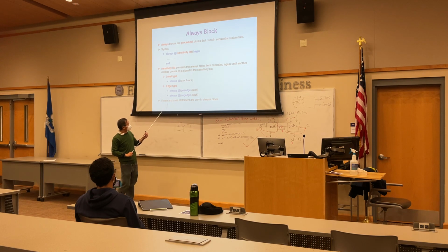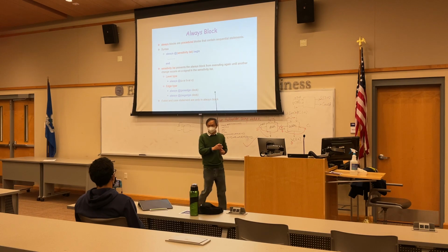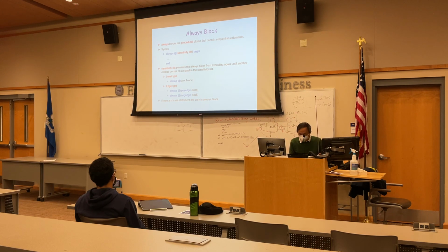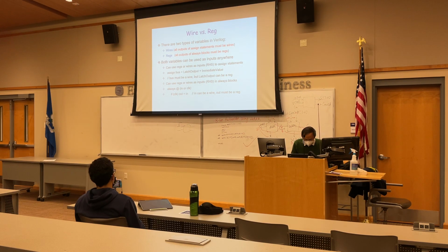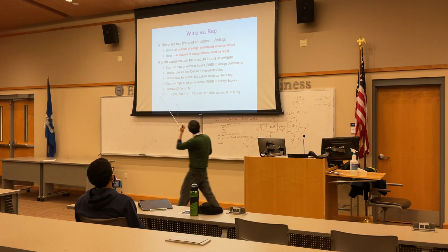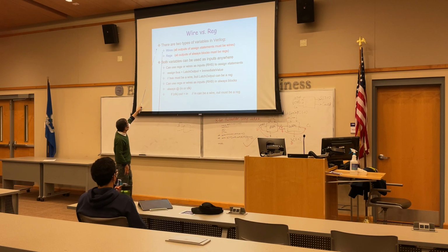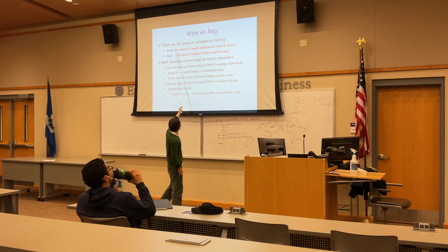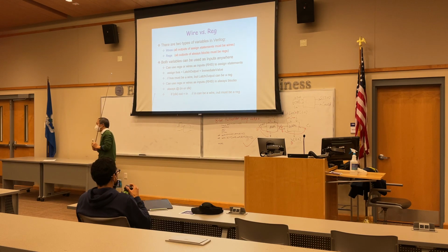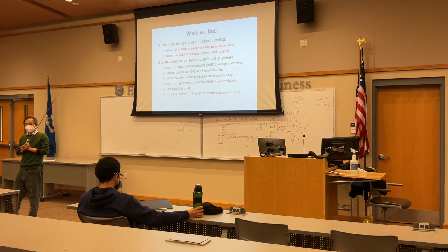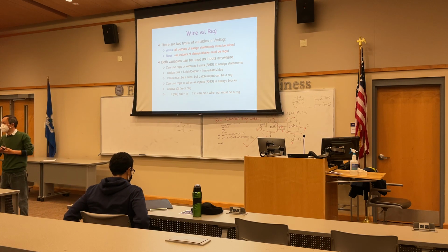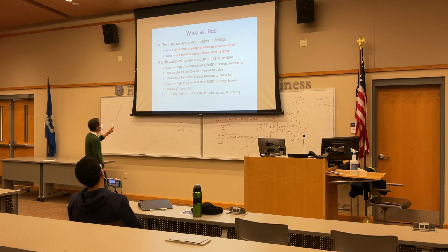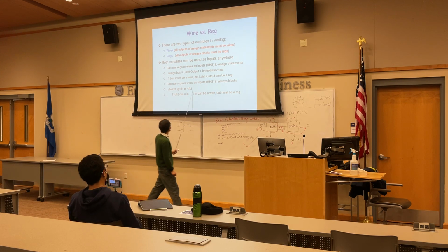If or else, the case statement, the branches, they are included in the always block. We're going to show you what we can do with this. So this shows the wire and register, right? When you define the wires and when you define the register, these two types will result in different outcomes. If you define it as a register, then when you do the synthesis, you are going to see a register. If it's a wire, then you just have a big wire connection in between.